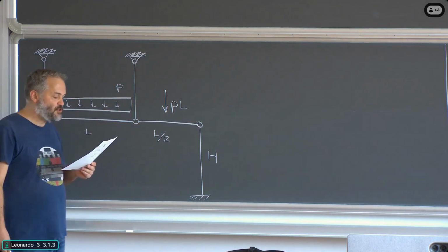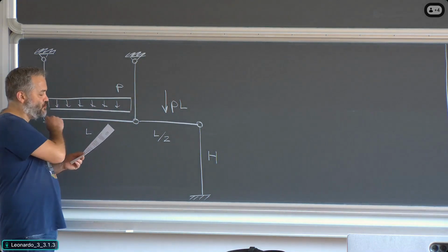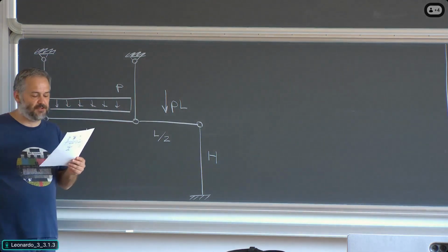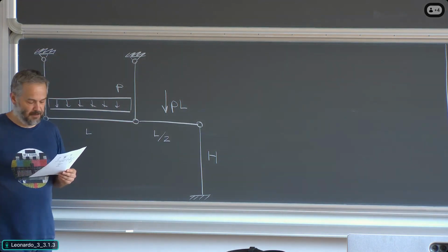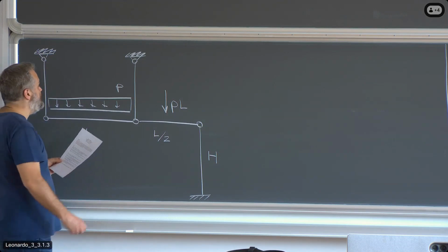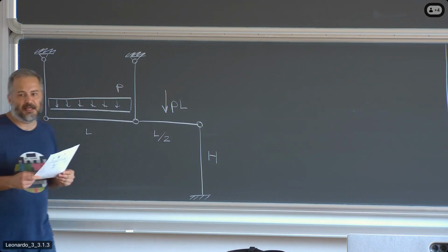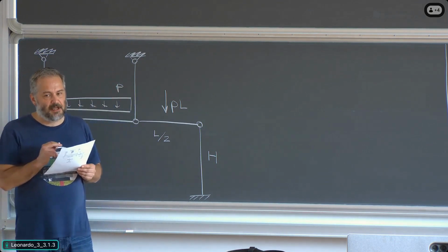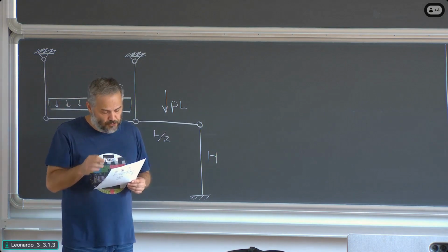Okay? So, first 2 points, read. Perform the structural analysis of the 2 beams, 1 and 2, by plotting the diagrams of the internal forces, shear and bending moment, as a function of P and L. Point B reads, determine the tension forces in the ties and the compression force in the column as a function of P and L. Now you have to be very careful when you read the assignment, because the assignment implicitly tells you what you should expect in terms of solution.